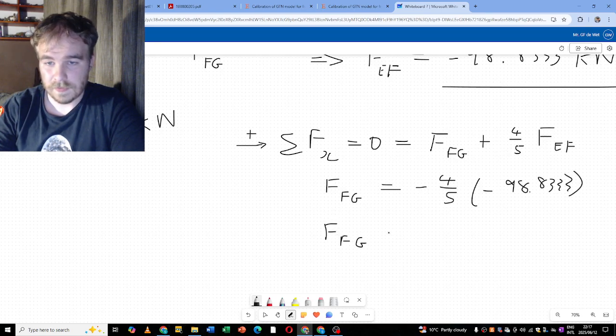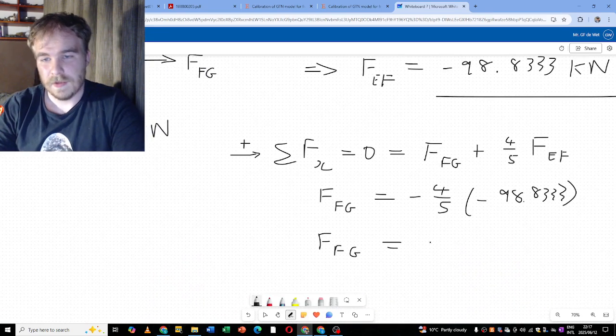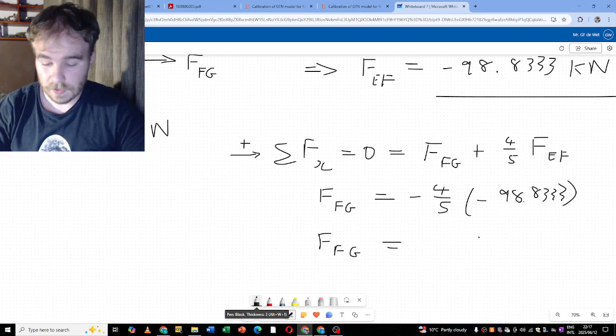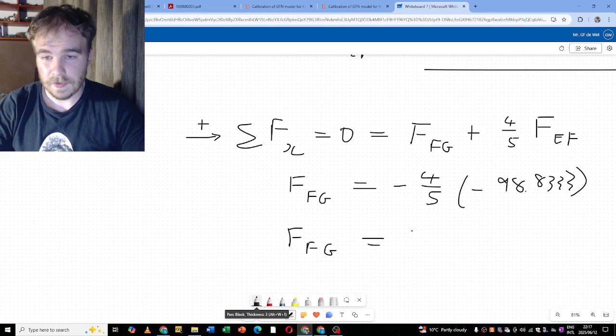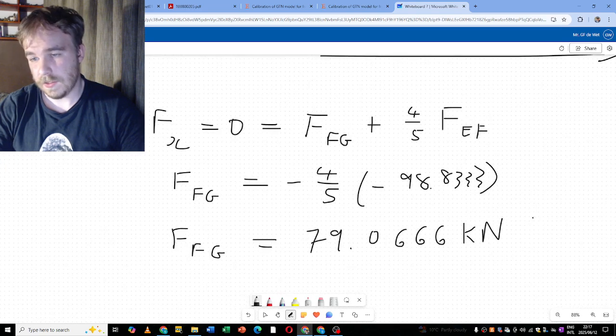Let me just double check that, 98.833, great. Then it's going to be a positive value, 4 over 5 times 98.8333. Then we get 79.0666 kilonewtons, which means it is in tension.